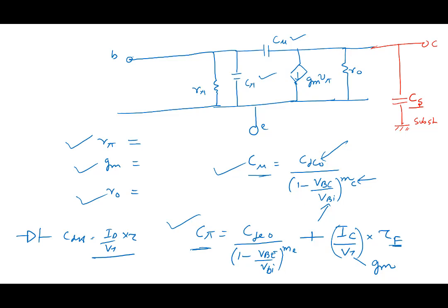You see that there's another capacitance between collector and ground. So this capacitor may also be there in some of the circuits that you're making, between the collector and the substrate. And because the substrate is DC, we put it to ground. So there's an additional capacitance from the collector to small signal ground here. All right, that's one thing.